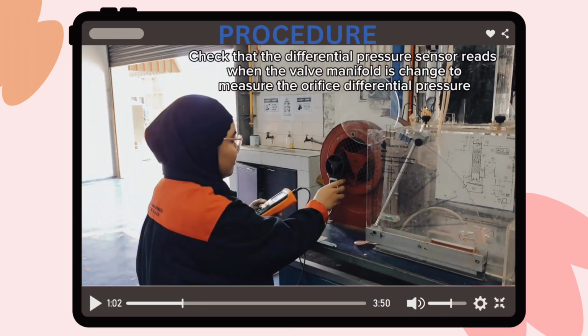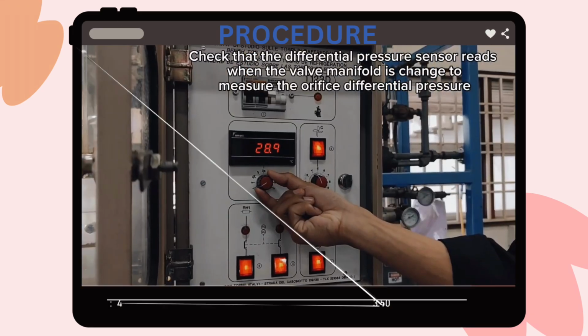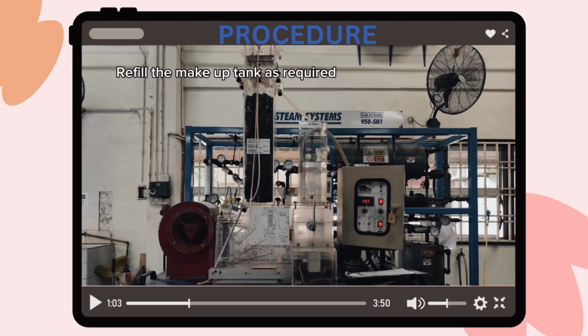Check that the differential pressure sensor reads when the valve manifold is changed to measure the orifice differential pressure. Let the unit run for about 20 minutes for the float valve to adjust the load tank's level correctly. Refill the makeup tank as required.